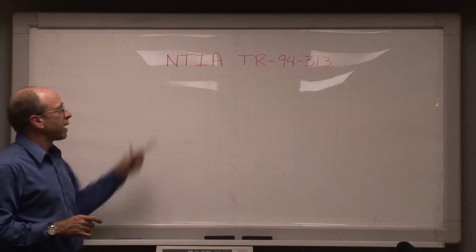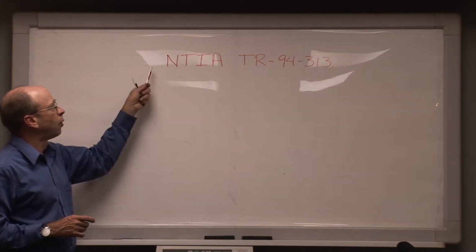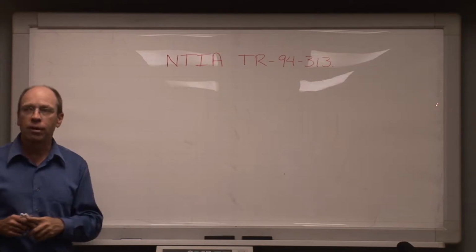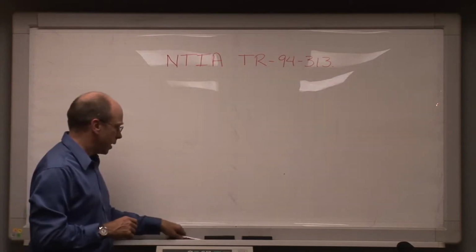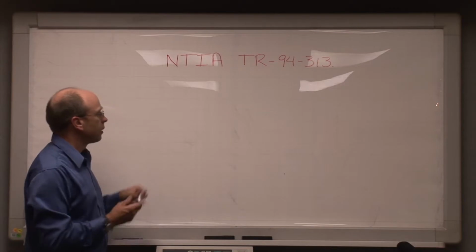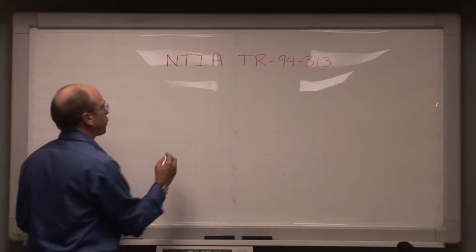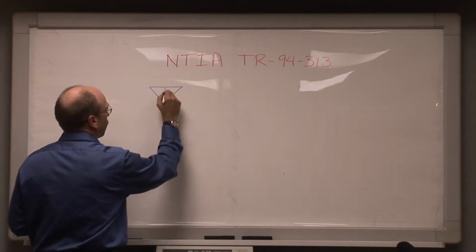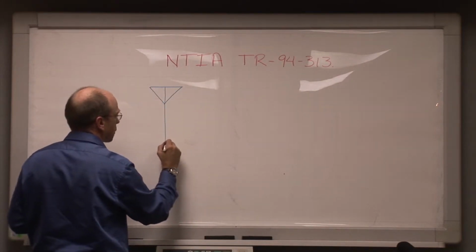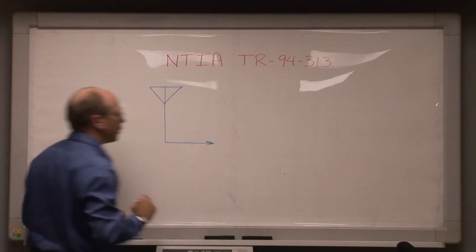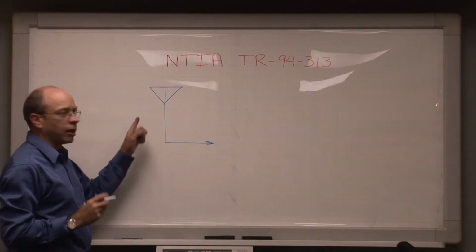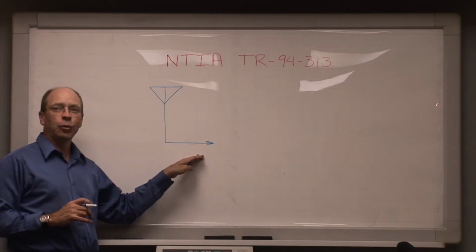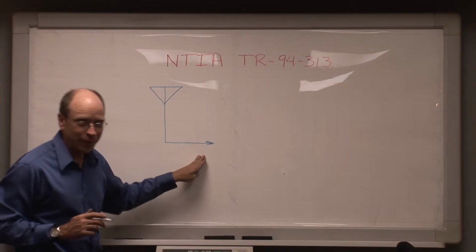What I'd like to talk about today are methods for identifying this interference mechanism and then what you need to do to resolve the interference mechanism. The first clue that you might have that you have a problem with RF overload is when you've been informed that a receiver is having an interference problem and you've called the people who operate the receiver and you've talked to them on the phone, you've gotten information from them, and among the pieces of information that you got were the schematic block diagram for the receiver.